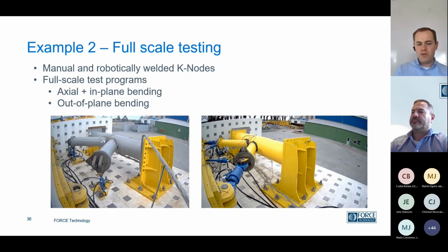We ran within our R ratio of 0.1. So we always had a tension load case. That was really to force crack opening. If we're going into compression, you can think about it as, for part of the stress cycle, closing the crack. That fatigue damage would still be counted, but it's more conservative to always do a tension load case. So that's what we did in both of these programs: tension load cases to really try and force that crack opening and force failure, because it does take time to get that failure in these specimens.